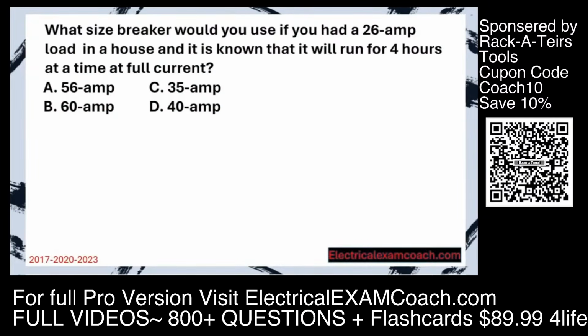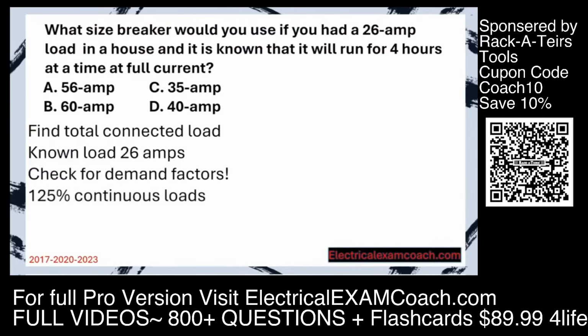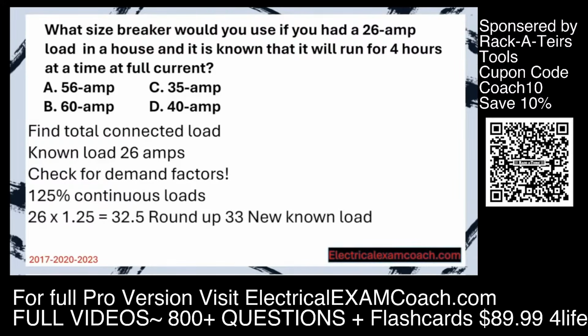What size breaker would you use if you had a 26 amp load in a house and it's known that it will run for 4 hours at a time at full current? Step 1, find the total connected load. Our known load as of right now is 26 amps. Now we got to check for demand factors. In this case, it's going to qualify as a continuous load. Any load that's expected to run for 3 or more hours at its full current must have that 125% continuous load multiplier. So we take our known load multiplied by 1.25. That gives us a new known load of 32.5. In that case, we would round up to 33, and that's our new known load.